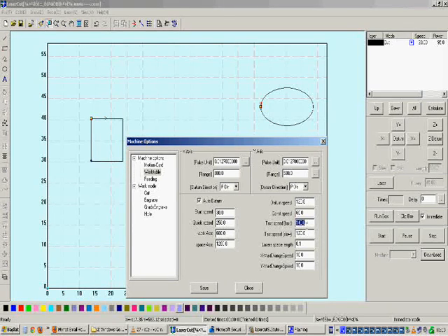So test speed fast is the test speed of the head when autodatum is clicked. If you did not click autodatum, then test speed slow is the speed that will be used in the test operation.